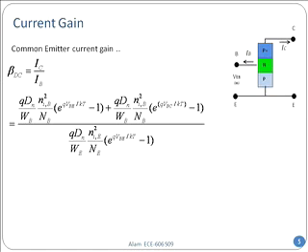Okay, I can insert those complicated expressions, but you realize that VBC on the numerator, that term, as soon as you have it in reverse bias, I just dropped it 2 seconds ago, right, in the previous slide, the second term on the numerator, and as a result, now I have a very simple expression. Do you see why? Because on the numerator, I have qVBE divided by kT on the first term. Look at the denominator. Again, I have qVBE divided by kT minus 1, because both are being governed by the base emitter junction. Electrons go easy, holes flow easy also.